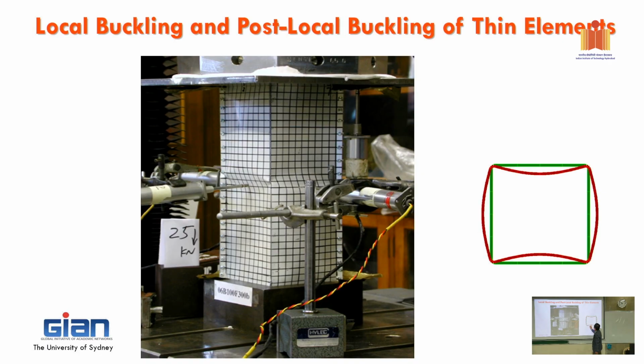In the plate here, if you cut the cross section, you can see that the buckle shape in that plate is a sine function, isn't it? It's local buckling. And because it's local buckling, the intersection line here is still straight. It's just happening in that plate only.